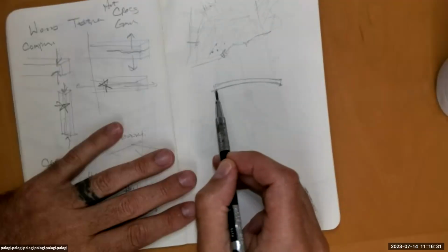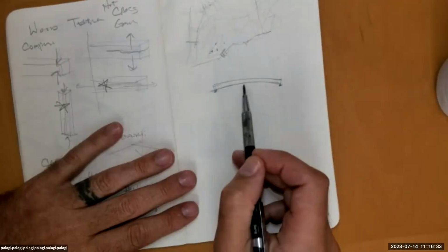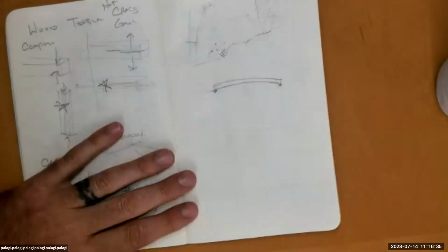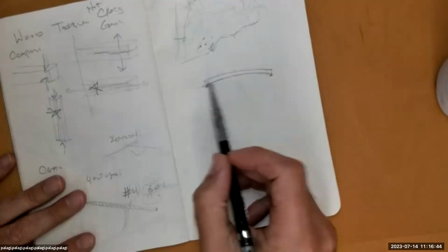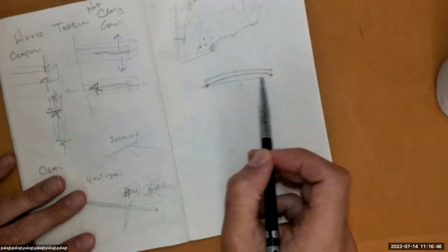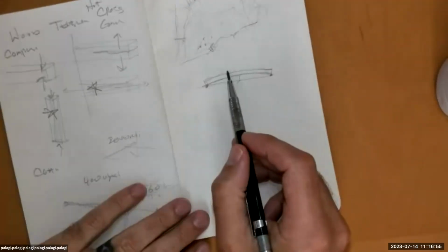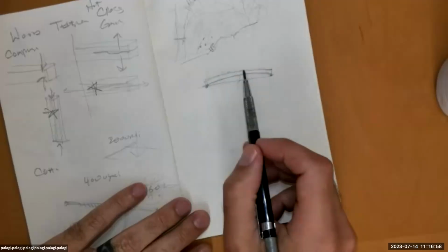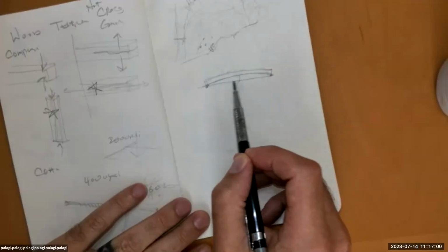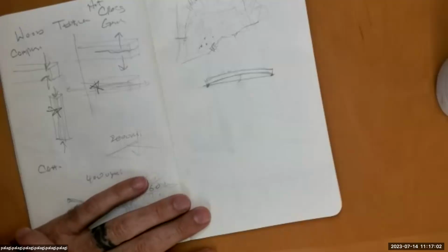Now, why would you get a beam pre-bent up when you want, let's say, a flat floor or a flat roof? Because once we actually put all the construction together, we want it to become flat, right? So this is engineered. As architects, we don't ever design that, but we would understand that this might come with a camber. And until all of the granite flooring or the concrete top or the equipment's there, it might not level out until all of that dead load's there.